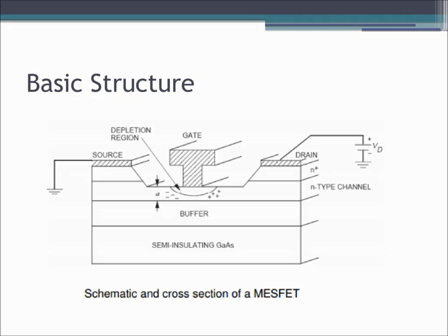The channel, or the conducting layer, is a thin, lightly doped conducting layer of semiconducting material, epitaxially grown over the buffer layer, since the electron mobility is approximately 20 times greater than the hole mobility for GaAs. The conducting channel is always N-type for microwave transistors.